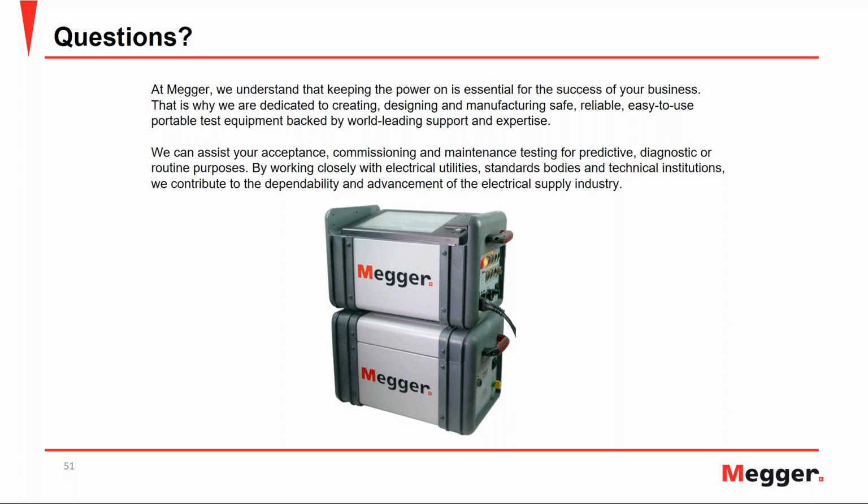But I would certainly say this: if you see an increase in trend of power factor values, then certainly you need to reduce your testing interval so that you can closely monitor how the values are changing over a period of time.